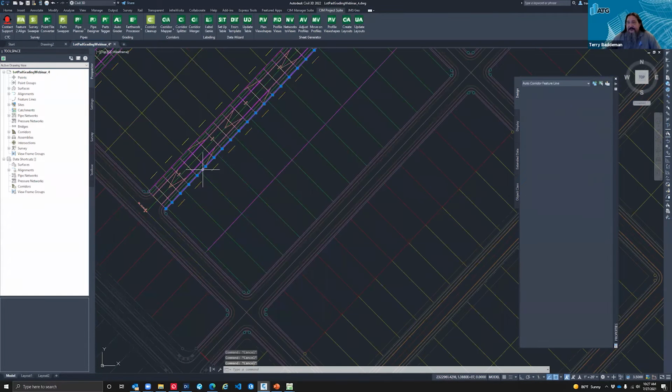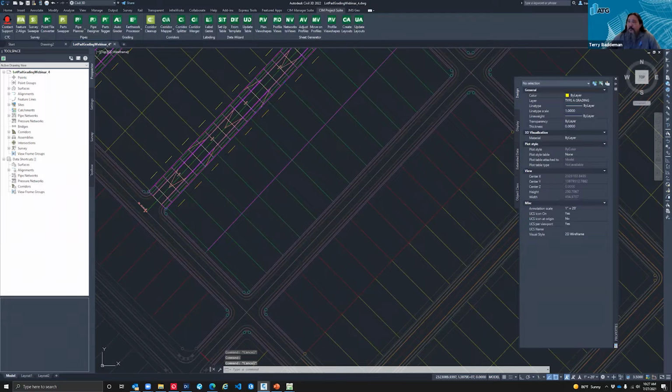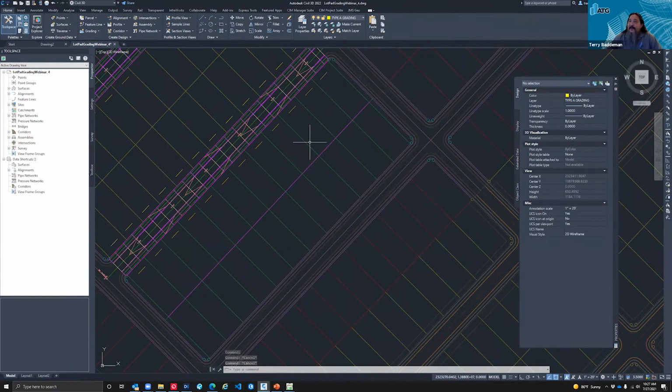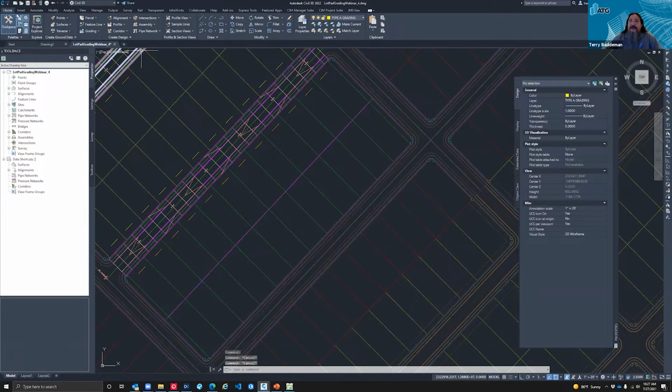So now that we have our control for our roadway, this is what it's going to use in order to develop our pads and our side lots. What we're going to do is take our lots out of our basic CAD drawing and create feature lines out of them. So we can go to our home tab, go to feature lines from objects. We can click on this little handy thing down here. It says XREF. So we'll click on our XREFs.